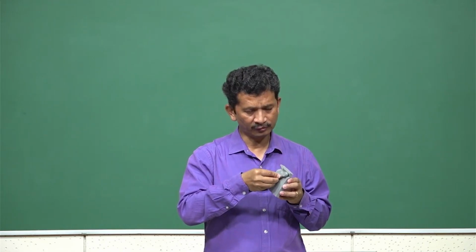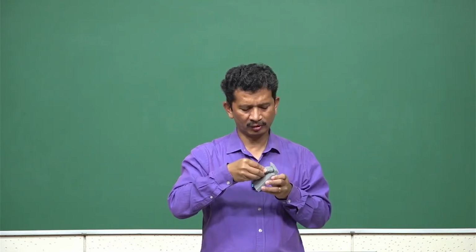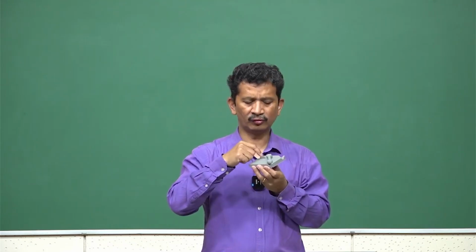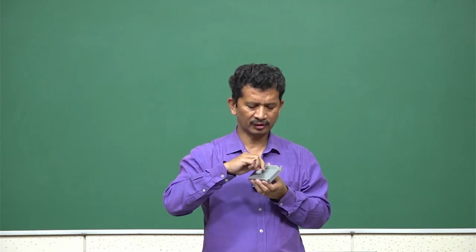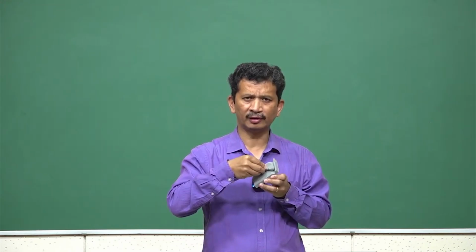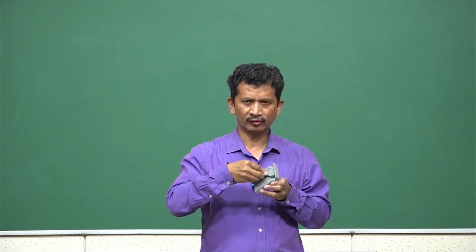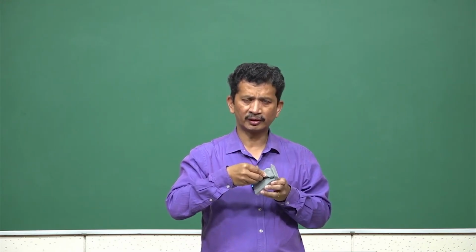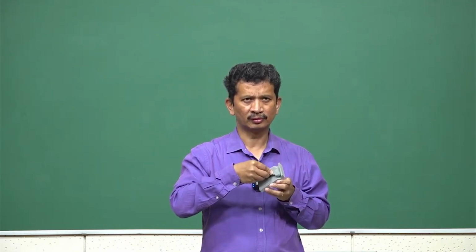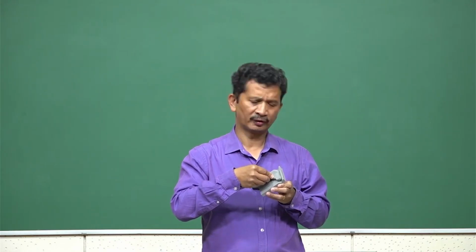Similarly, the moment it falls into another V groove, I have like 2 V grooves, one this and the other here, and if I just press them so that they are always in contact, that gives 4 contacts. So, 4 degrees of freedom, 4 constraints.